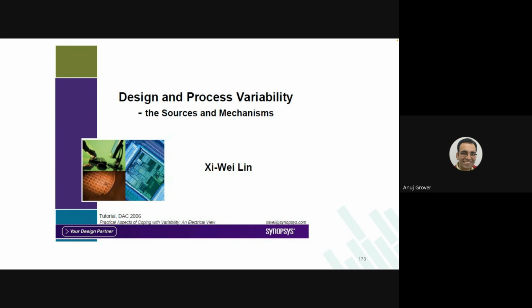And the margin related to these random mismatches, you simply cannot do away with. You have to ensure that these mismatches are very well margined into your design, that your design should not fail in the presence of these random variations. It is for this that you have to do Monte Carlo, not for estimating power. Is it okay?